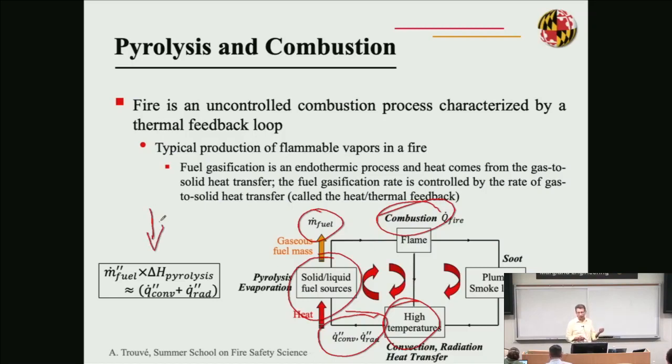Typically in the context of evaporation, if you look at the evaporation of water, you're going to say, well, let's look at the rate of heat transfer that goes back to a surface of water, okay? And that's a heat flux in units of kilowatt per meter square of the pool of water surface. Assuming that all of this heat is used for evaporation, you can have the rate of evaporation here in units of kilogram per second per meter square.